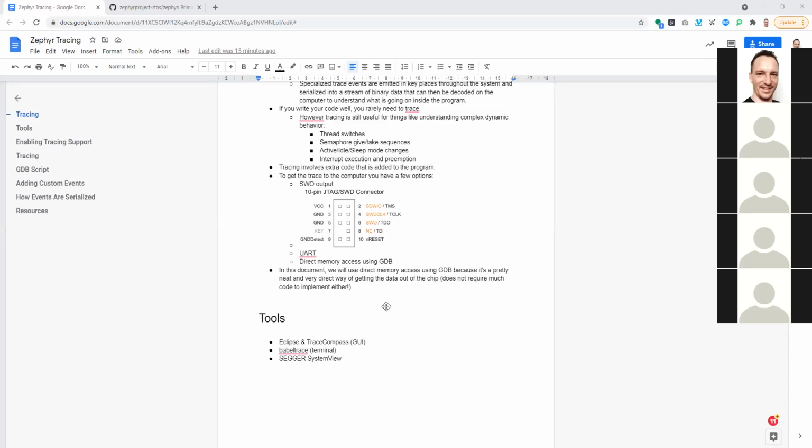And this FIFO functionality is very useful when you have bursts of events. So, for example, if you need to send a number of events very quickly, and then there is a period of time where you're not sending any events, then the SWO pin can be filled up with data, and then it will start transmitting the data to the debugger, and your code can continue executing, and then you can send more events to this port.